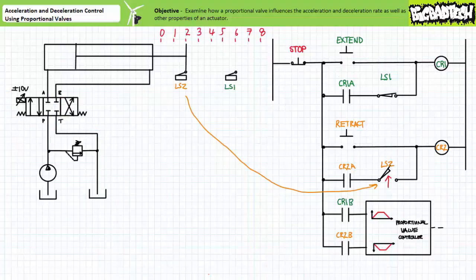Flow slams to a halt, as does the applied load. Pressure upstream of the proportional valve spikes to that of the main pressure relief valve. The rod stops 2 inches from full retraction. Again, quite obviously, we failed to meet every qualification during the retraction phase. 1. The applied load didn't accelerate or decelerate smoothly, but rather jerked to a start and slammed to a stop. 2. The pressure dropped, then spiked. Finally, 3. The rod failed to fully retract.